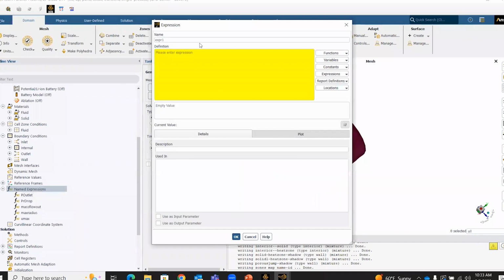And we calculate another expression, which is the radius of the inlet. Now, this is what makes it a multi-valued expression, because remember, the inlet boundary consists of multiple faces from the mesh that is used to describe that particular boundary, okay? So at every face center, your coordinate of X, Y, Z is going to be different. So how do you calculate the radius at any point? You use the same mathematical expression that you would when you're doing hand calculations, right? So it's going to be the square root of x squared plus z squared, okay?